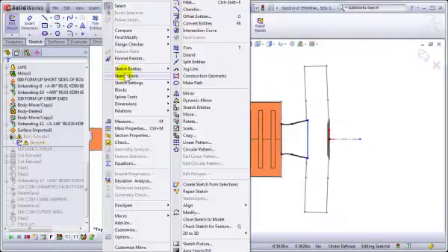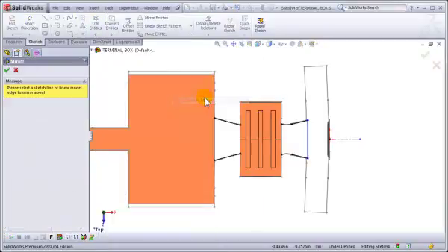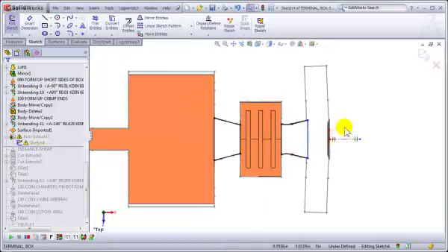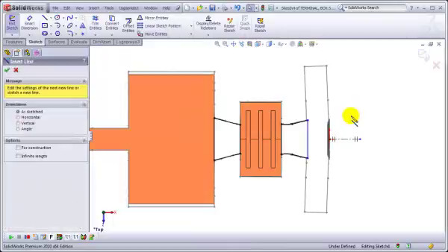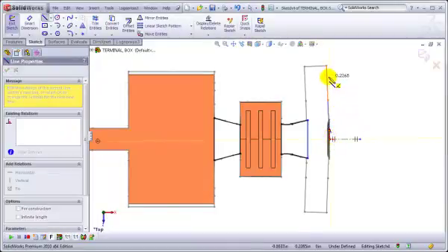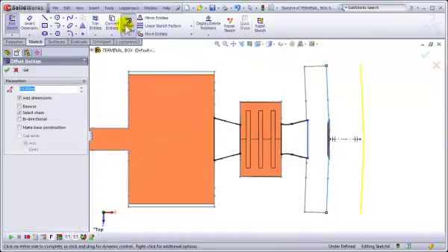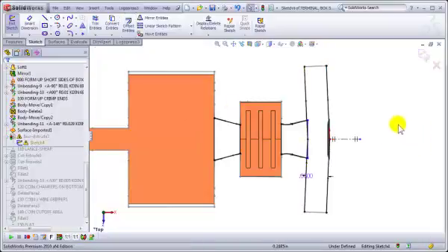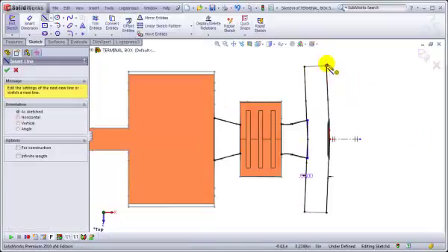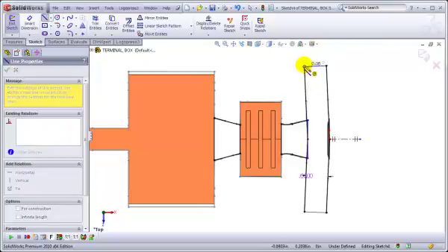And now we will set our sketch to dynamically mirror about that center line and use a shortcut key to draw a line from here to here. I simply type L on my keyboard, and we'll offset that by 80 thousandths. I know already that that's how wide that was. Reverse it. And finally a line across the top.